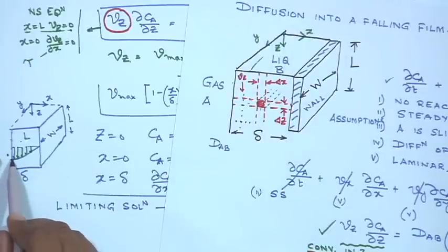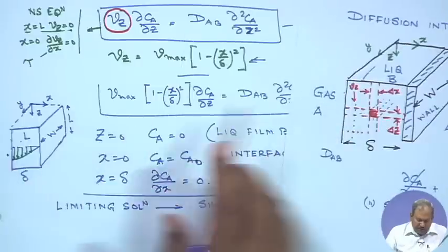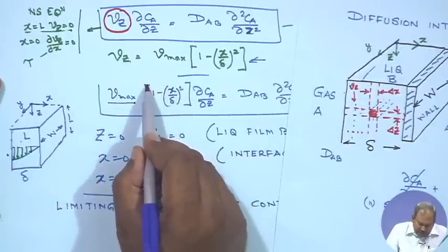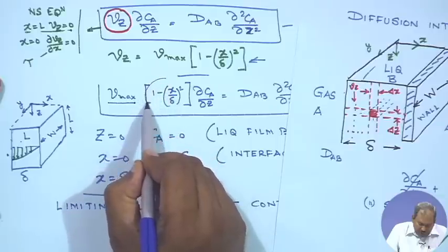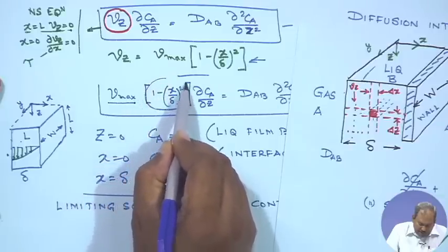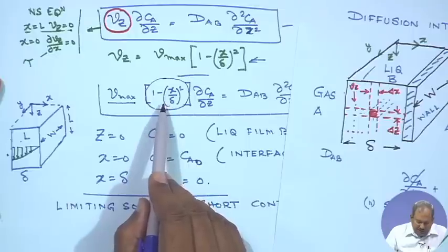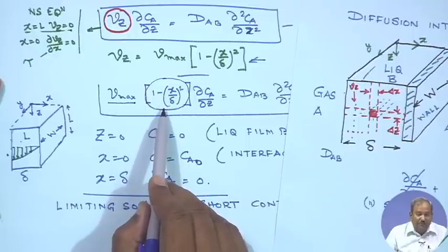It is because of the nature of the velocity profile, and as if the entire film is falling with a constant Vmax, and the variation of V with x, to the diffusing molecules, is as good as absent.